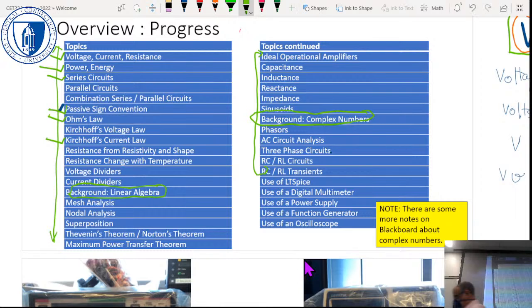These five, F, G, H, I, and J, are all connected together, but the next row up are also all connected together in a row, but they're not connected to the row below or the row above. Holes A, B, C, D, and E are all connected together, but not to the ones above, and not to F, G, H, and I. The reason why that is, we're not going to use them in this course, I don't think.